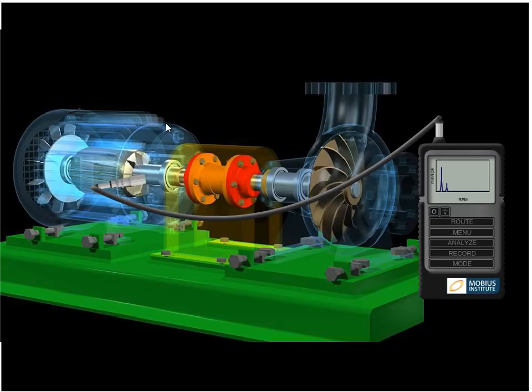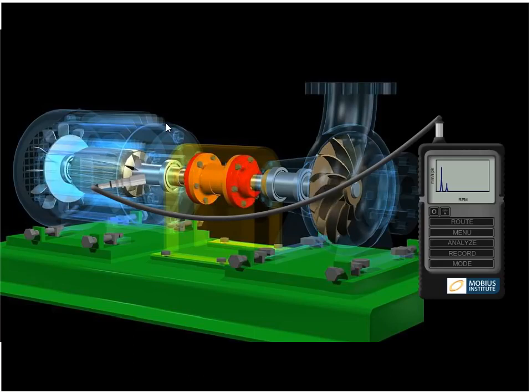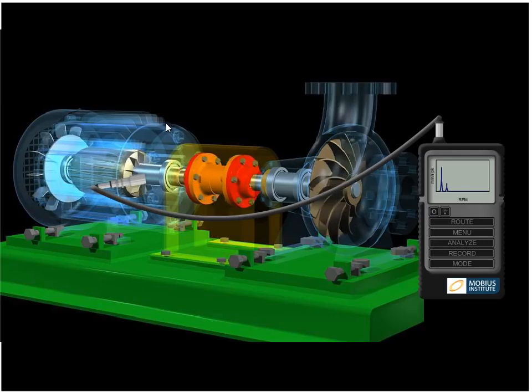So, for example, if it was rocking back and forward due to looseness or resonance, then the horizontal measurement will tell us about that. And whether it's vertical or horizontal, those two positions tell us about radial vibration radiating out. So if there was misalignment, offset or parallel misalignment, or unbalance, we get a lot of that sort of up and down and side to side motion. But with angular misalignment, for example, and certain types of bearing faults, it's more sensitive in the axial direction.